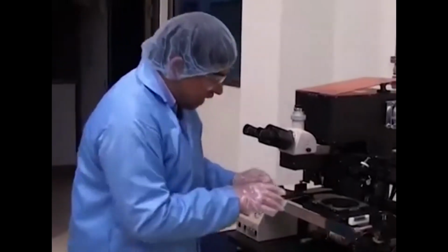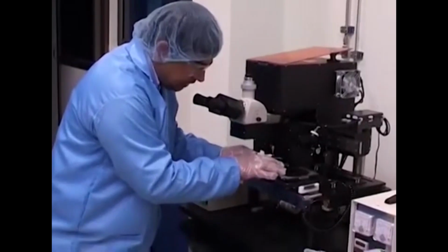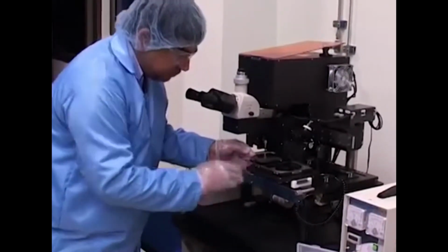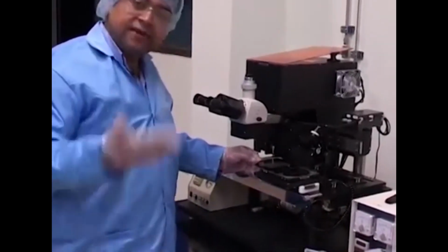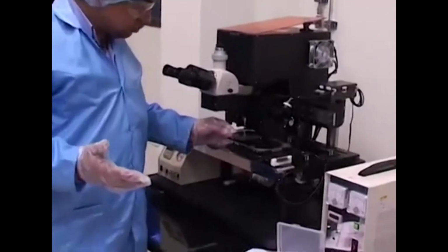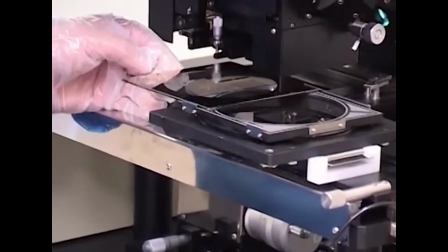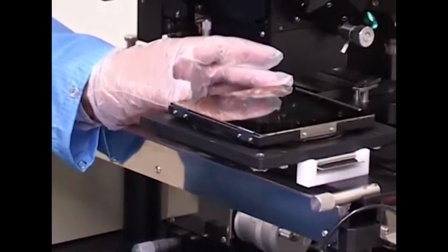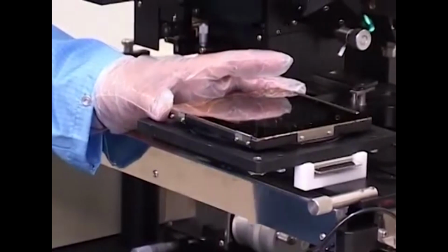So what I am going to do is actually align this mask in its place here. There are two slots for that purpose, and I am going to make it face down. The chromium side has to be facing the wafer surface, which is given by this dark brown region of the mask. So I slowly put it inside the mask holder, and this is only a passive gripping.